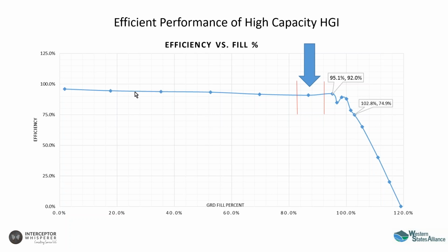All of the legacy style hydromechanicals, formerly called grease traps, it was James Baginski in Hawaii who actually first discovered a ratio when he was developing the 25% rule, and he's really the first proponent of this concept of a rule of thumb for gravity grease interceptor pump out scheduling. And it was, how do I know if a gravity grease interceptor is full? And he didn't have any way of knowing that because they're not performance tested, so you couldn't look at a test report and discover that.